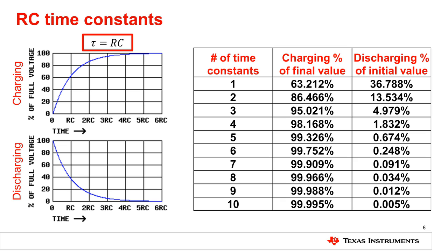Regardless of the values of the resistor and capacitor in an RC circuit, the response will have the same exponential form. However, the resistor and the capacitor will determine the time it takes the capacitor to approach its final voltage level. This time is often measured in RC time constants, which are represented by the letter tau.